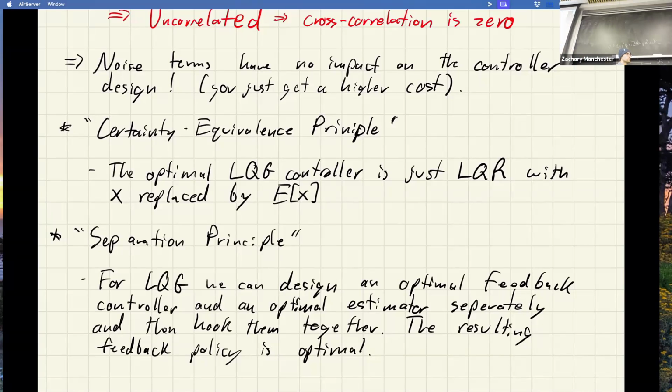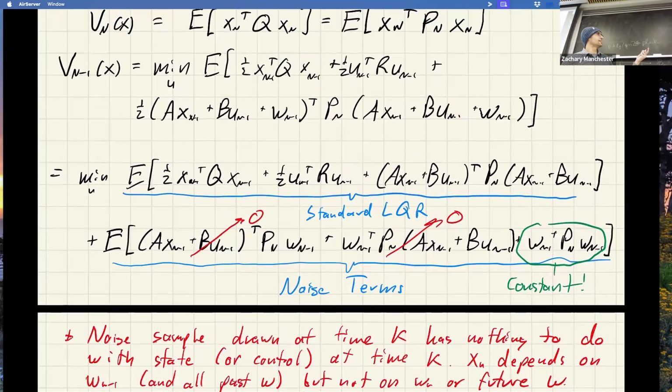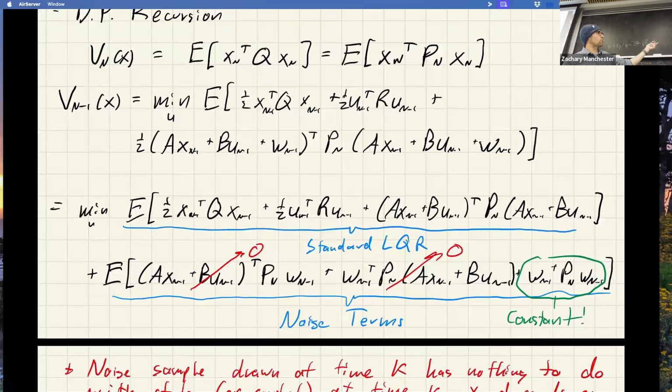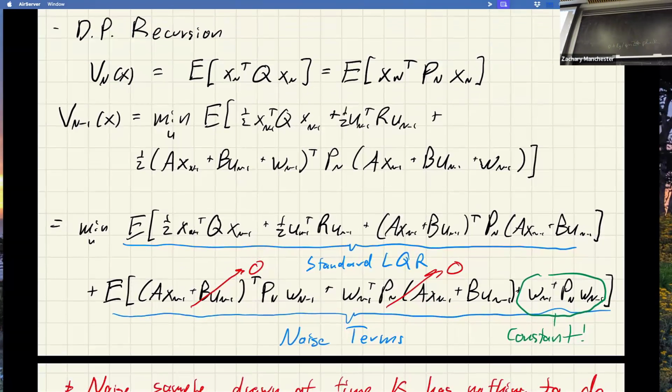So literally it's a constant. That's what we showed, right? So it doesn't do anything. It drops out. Remember, when I solve for the controller here, it literally has no impact at all. So I can leave it in there, but as soon as I solve for the matrix in the Riccati thing, the constant term drops out and does nothing, right?